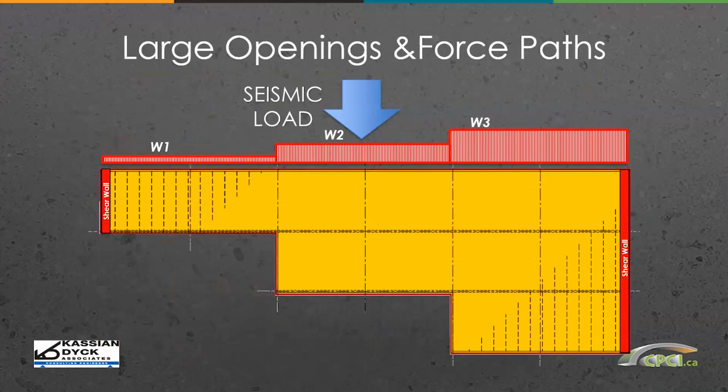Similarly, if you had a building in plan view looking like this, that would be a nasty beam to design if your support was on the left and the right. You'd have to look at how you're going to design that beam, how you're going to drag the forces to where you want them. Do you have tension reinforcement and shear reinforcement properly designed in the various regions of the beams? So again, you need to think of the diaphragm beams as a beam and just design appropriately.